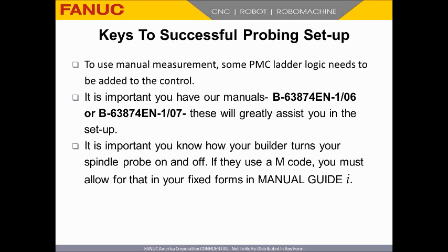And the reason I know that is because I've done it myself before, where I've worked on certain machines where I thought an M code was going to turn it on, that didn't. So it's critical that you know what that M code is and then that you implement it whenever you want to use a probe. So if you're going to do manual cycles, you have to go in MDI and turn the probe on first. Okay? Again, I want to emphasize that. Make sure that you know what that is and either make a fix form for the automatic side, or when you're doing the manual side, you go into MDI and turn it on first.